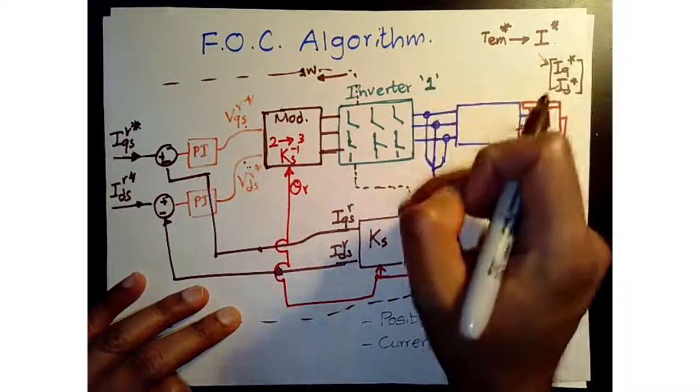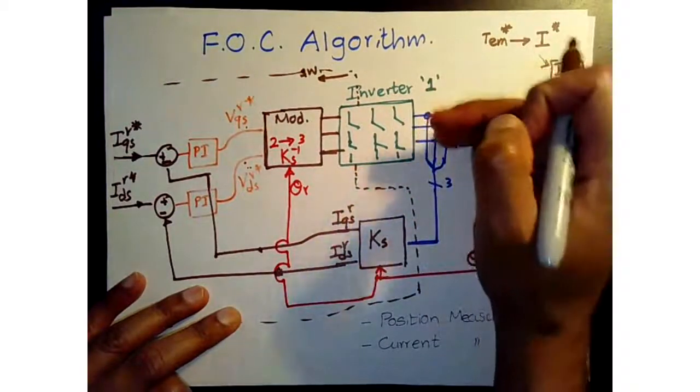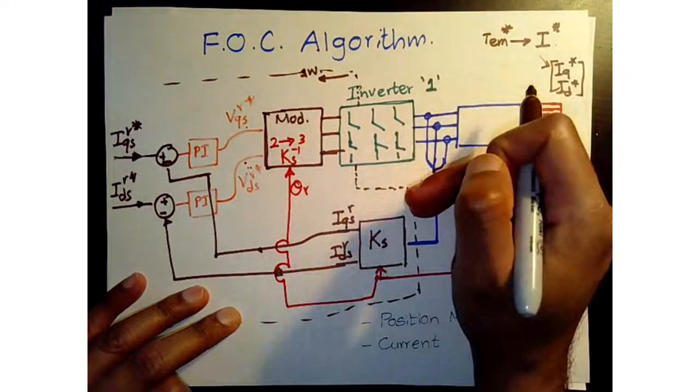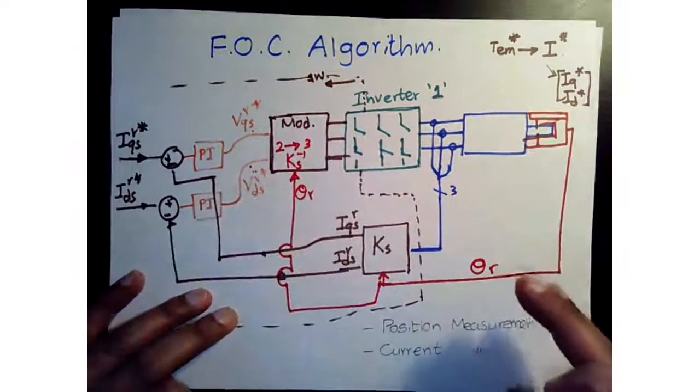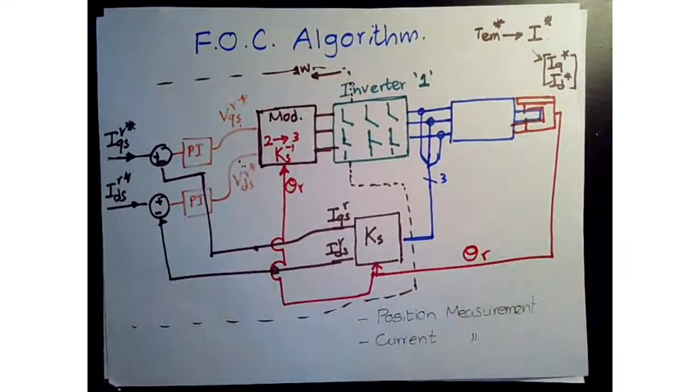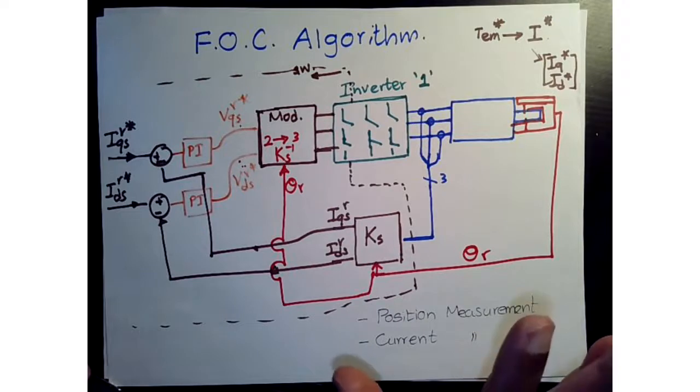So it's going to look similar to controlling a DC motor, but now you have two differential equations, so you have two controllers. Close enough, right? Zero sequence is not generally considered because we assume a balanced system for the most part. If you have a fault or some other nonlinearity, those things violate that rule, and then you have to think how the nonlinearities will affect your overall system. That's a different discussion, a more advanced discussion.